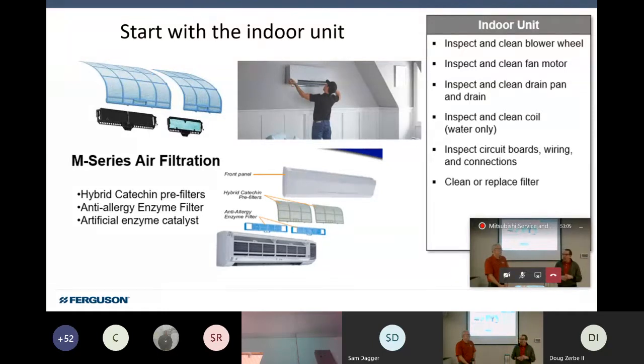But think about this: if I'm getting variable frequencies of flow of refrigerant in that coil, sometimes the condensation taking place on the coil may not be 100% of that coil. It's true. And we get areas of the coil that are not truly condensating with the moisture, also depending on the humidity level in the room.